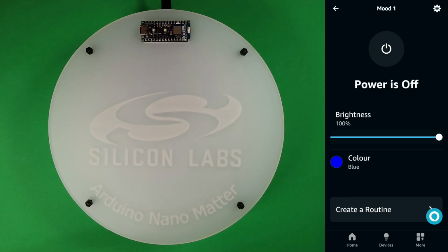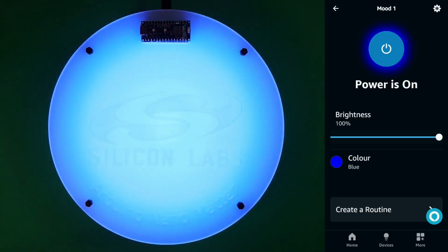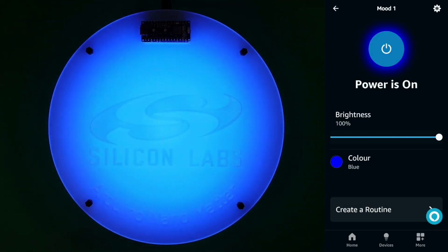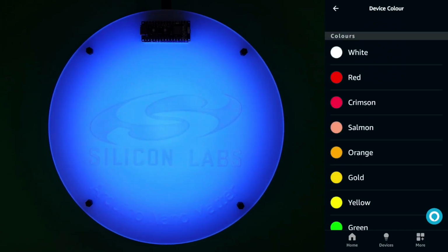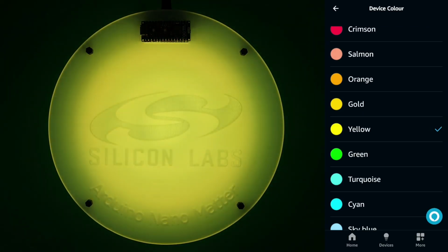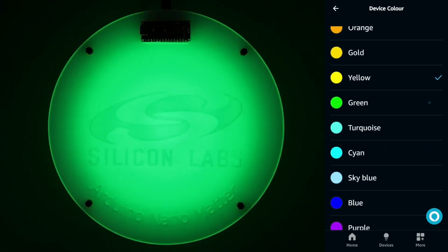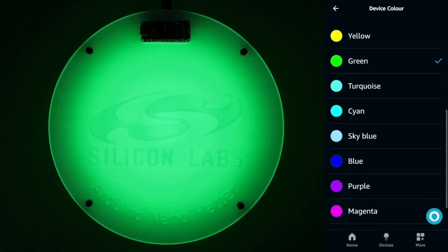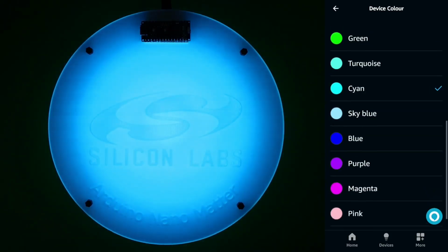Let's start with the first step, which is mainly concerned with making sure the Matter device is set up correctly, ensuring it can join a network and that the two color bulb endpoints can be used to change the two colors in the device. We'll have two modes, selected with a button press, that swap the LEDs between the first and second endpoint colors.